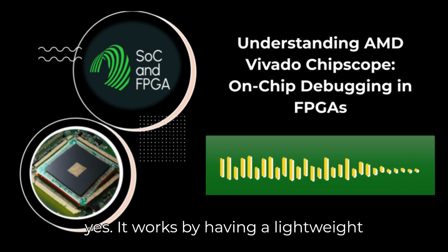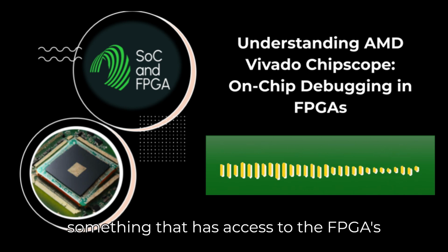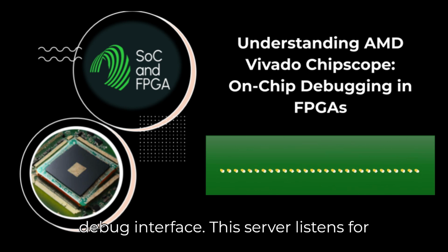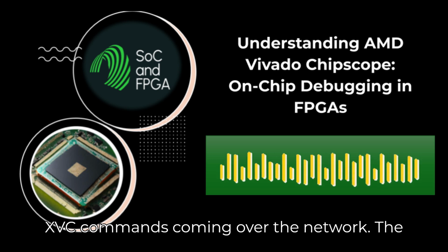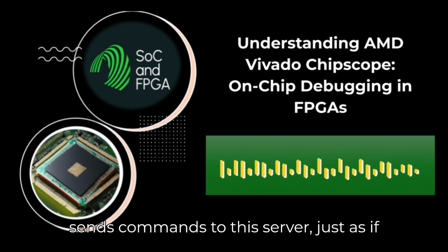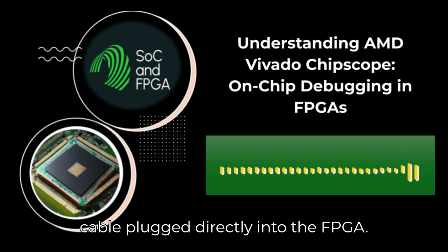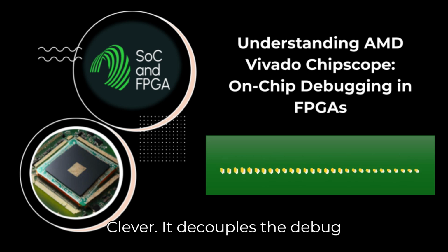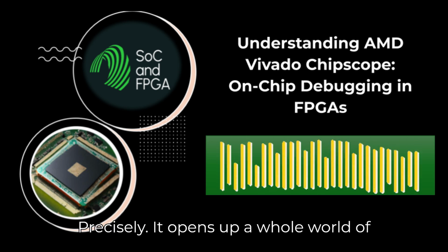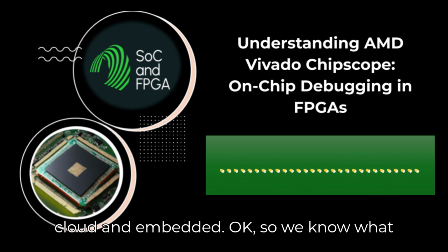Essentially, yes. It works by having a lightweight server running on the target system, something that has access to the FPGA's debug interface. This server listens for XVC commands coming over the network. The remote Vivado hardware manager then sends commands to this server, just as if it were talking to a physical programming cable plugged directly into the FPGA. Clever. It decouples the debug software from the physical connection. Precisely. It opens up a whole world of remote debugging possibilities. Huge for cloud and embedded.